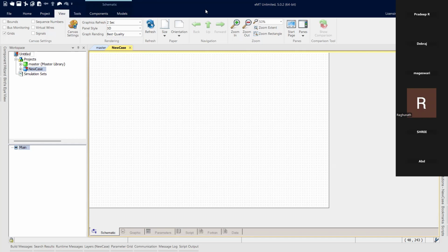And if you are including a frequency dependent model of cable or transmission line, PSCAD itself would recommend you to go below this time step for accurate capturing of the results. So that depends on your studies. You can determine the solution time step. I hope you are clear, Stalin. So if you have got that correct, oh yeah, thank you.